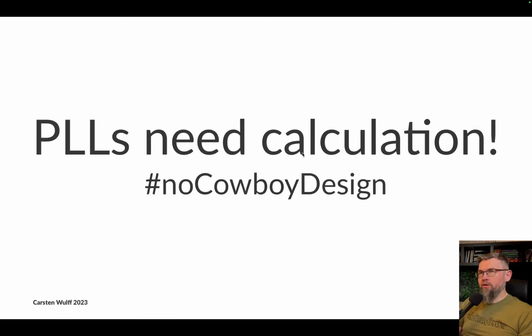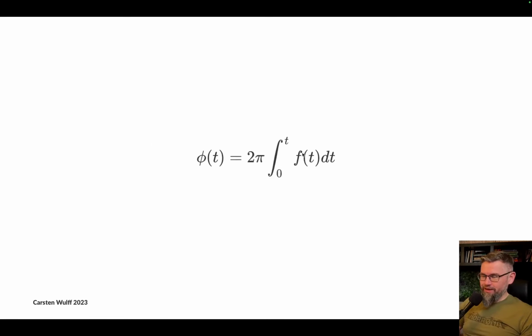So it's one of the few analog designs where you simply cannot do a cowboy design. What I mean by cowboy design is that you sit down, you throw some transistors together, and you hope for the best, which actually works with a lot of analog design, but for PLLs, forget about it. Will not work. You have to analyze them.